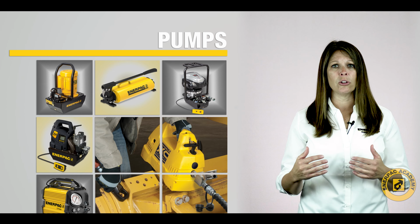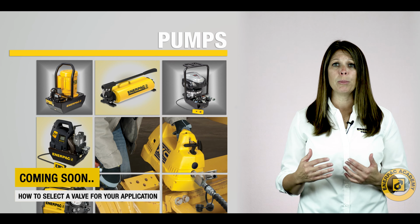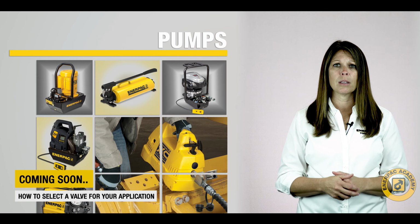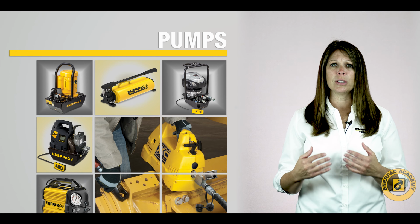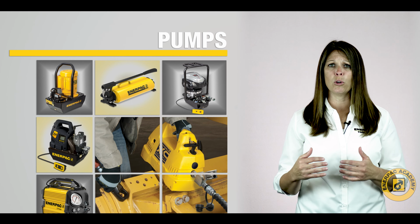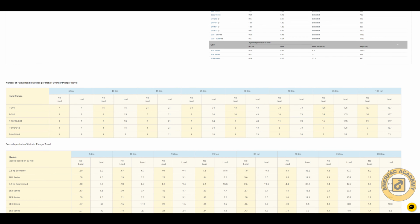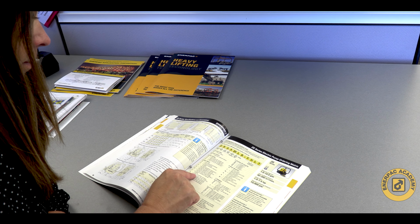Valve type is another term used in pump selection. This is a larger discussion and will be covered in another video series on valve requirements. By using the pump flow and pressure information and your cylinder specifications, you can calculate your system speed and force performance using the pump and cylinder speed charts and formulas found on Enerpac.com or in your Enerpac catalog yellow pages.